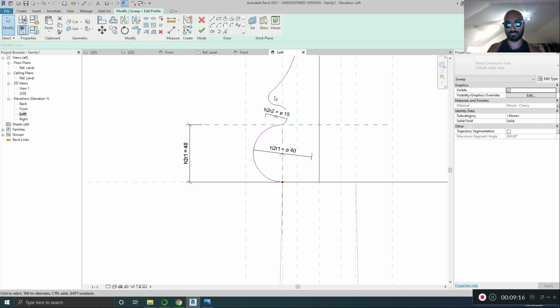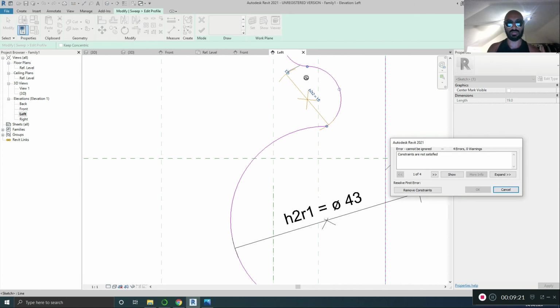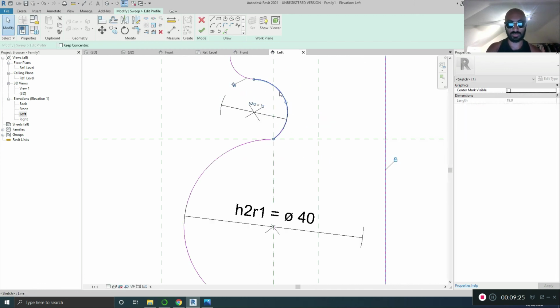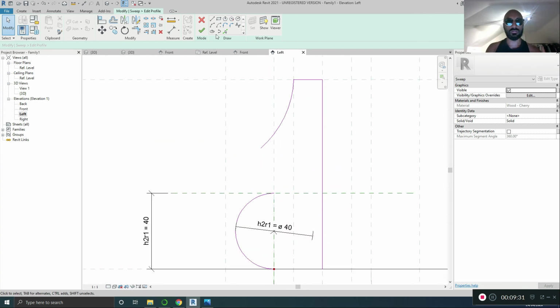Sorry, I'm going to get into that in a minute. This one I'm just going to undo, cancel. Delete that. And delete this. I need to put another arc down. Tangent it. And AL for align that to that and lock. So that it's aligned to the reference plane only and not to this. You align them to each other, you got trouble, just like I did.